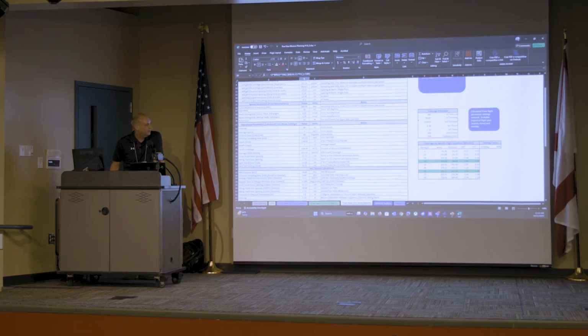So in a flight of between 20 and 25 minutes, that's basically what we have flying with the Matrice DJI M300. This is the aircraft, the drone that they have. So you can see that in, let's say, 25 minutes, we're going to have like 80 hectares per flight. So that's pretty good.